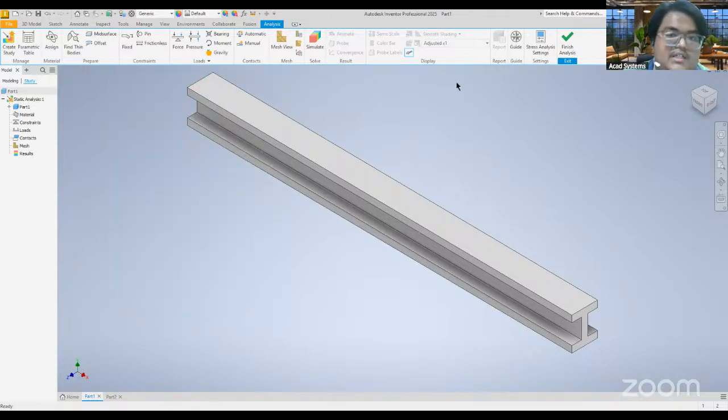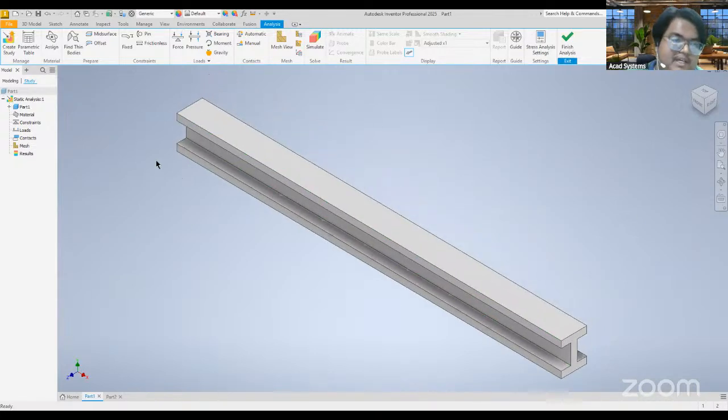And so here are the things that you need. So firstly, usually what happens is here we have preparation. You prepare your parts in order to make the analysis go faster usually. So usually, let's say you have a really complex shape over here, it's best for you to simplify it down first. Let's say maybe you have some fillets that are more cosmetic, you can remove those, and so on and so forth.